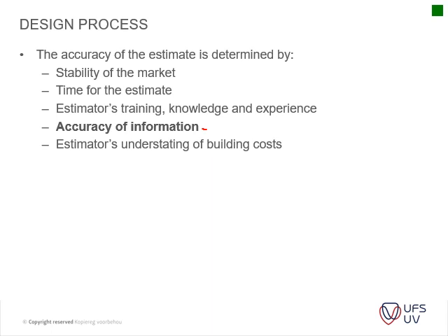So we actually saved a lot of money because the tiling area was such a large area. We could rather put in the PVC expansion joint instead of the stainless steel one, and we still got the same look and feel by just looking at the color of the PVC one that we put in. So those are options that one can actually look at when you do your estimation and so on.